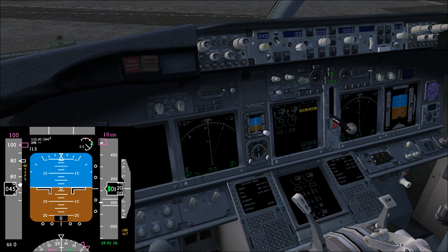The no V-speed indicator actually shows that we have not set the V-speeds, so no V1, no V-rotate, no V2 on this aircraft, and we have later, for the last part, a magenta indicator. This magenta indicator actually shows the commanded speed by the speed window here, so by the knob, or the actual FMS selected speed. Actually, this speed can be passed in Mach. These indicators show the speed, and here up we have the actual speed in digital readout.